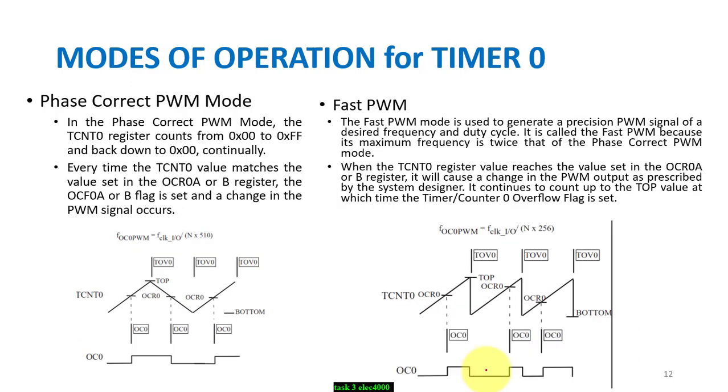Now over here it's a little bit different story, because the timer is not interrupted. Timer counter will count from 0 till top, then 0 till top, then from top to 0, and so on. Now once your timer reaches the value of output compare register A or B, it will give an output signal which is flip the output signal, the right word. It will toggle the output signal.